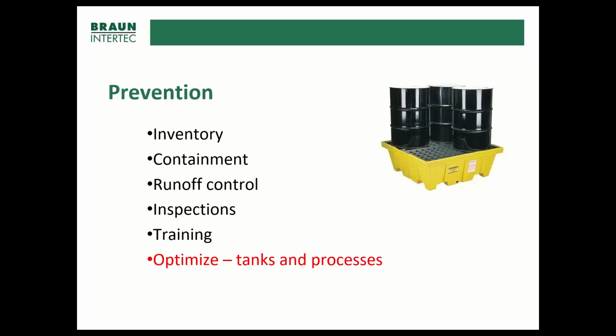So moving on. An important part of the SPCC rule is, of course, preventing spills. We're going to do this in a variety of ways through a plan. One way is through inventory management, making sure that we've got a complete list of what we have stored on site, focusing on the containers that are 55 gallons or more, and then making sure that we have the right containment.